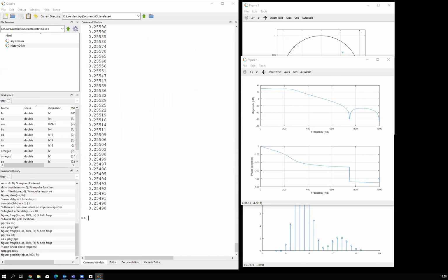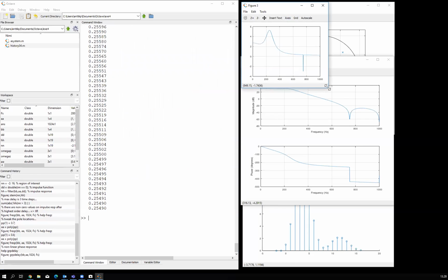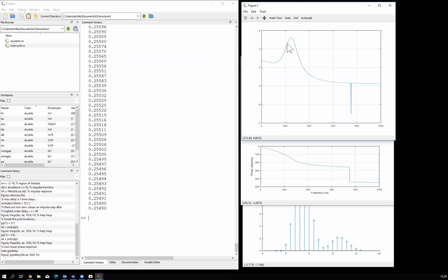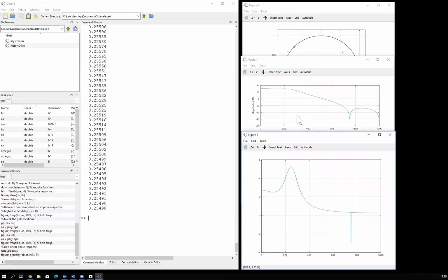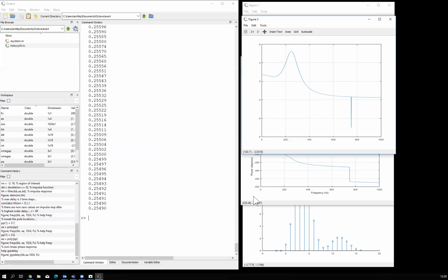When I talk about nonlinear phase response, this is now the time delay of the signal in some samples, I think so, but we have a 2 kilohertz signal, the sampling rate, so each time step is 0.5 milliseconds. So practically we have about 1 millisecond to 1.5 millisecond. Oh, actually, let's see, that's 2 milliseconds. Oh, yeah, 2.5 millisecond, in between 1 and 2.5 millisecond time delay in the passband. So group delay done like that.